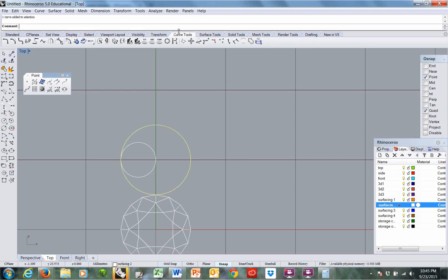Going to offset my curve, through point option, T enter. Now I will use center. I'll go ahead and leave 3 options open. But I have to be more careful now because I can hit quad very easily. Okay? Make sure it says CEN there in the little window and click. I can delete that reference curve. Alright?